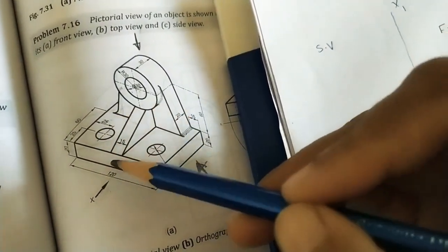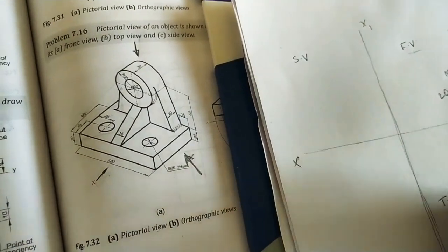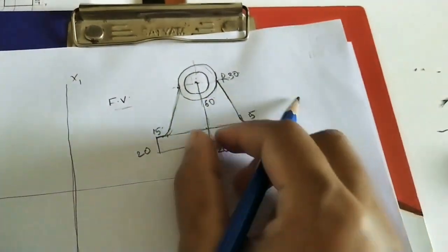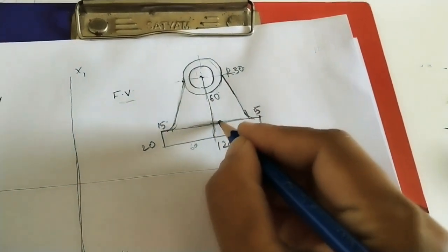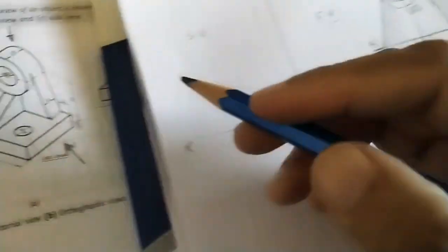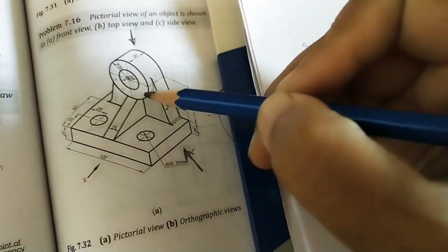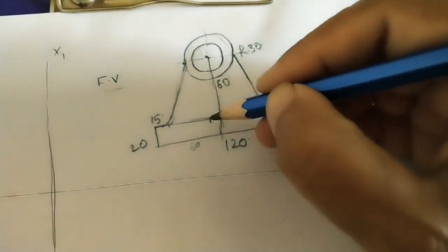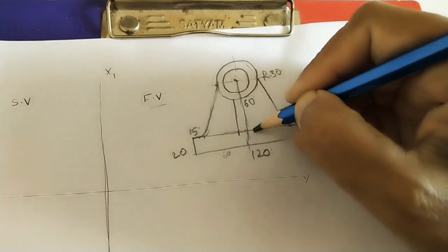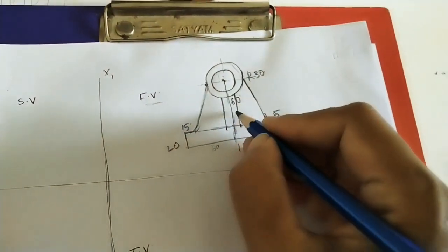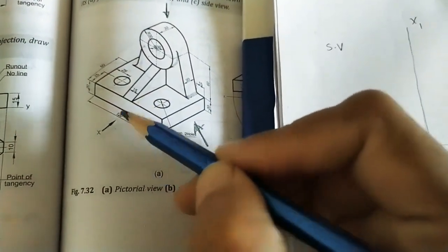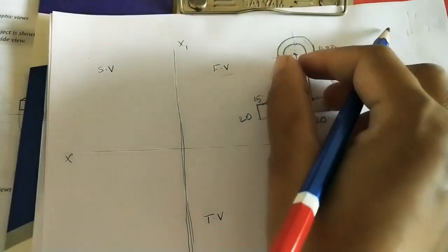At the middle of the circle, instead of a slope we can see straight lines. So already we did the middle line here. So a 15 mm thickness line means this side 7.5 mm, this side 7.5 mm. By using a scale, mark these points and then draw these lines from this bigger circle, joining to the bigger circle by using a scale. So the total thickness is 15 mm, correct? So in the front view we can see these lines as vertical lines.